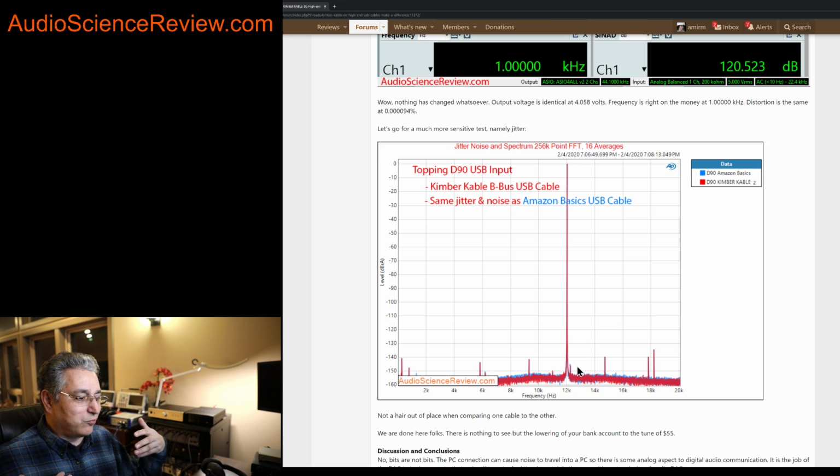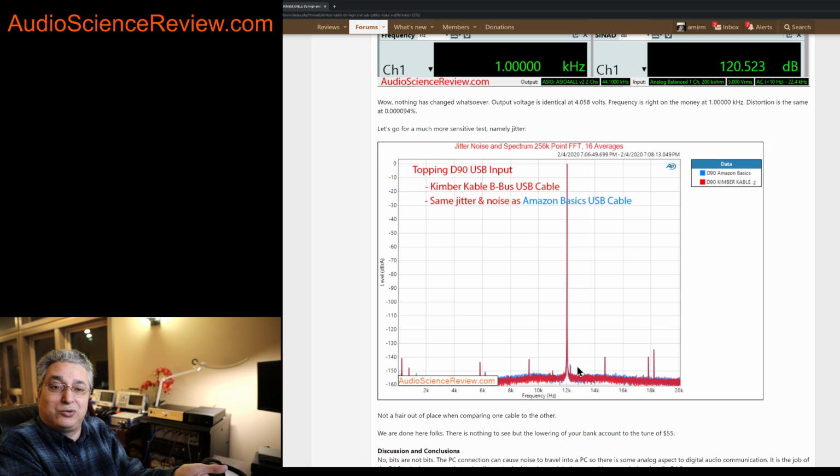This is when you buy a proper desktop DAC that I recommend to you, it does all this stuff. They know USB is not clean. I mean, it takes 2 seconds to put a scope on a USB cable, find out it's not clean. Well, you don't use that voltage as is. You bring it in. They have DC to DC converters that convert that to other, or in this case, may not even use the 5 volt off of a USB anyway.